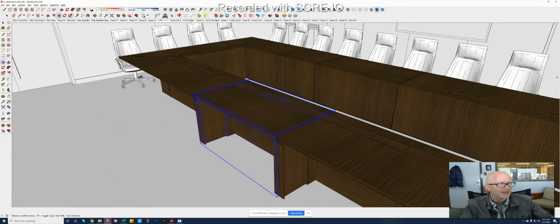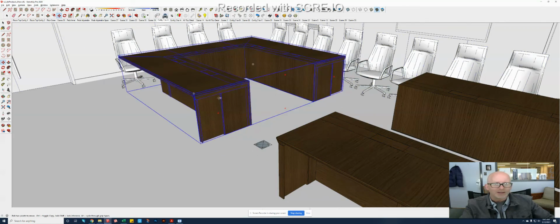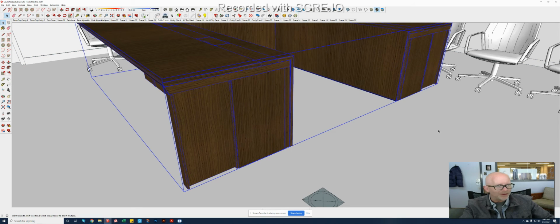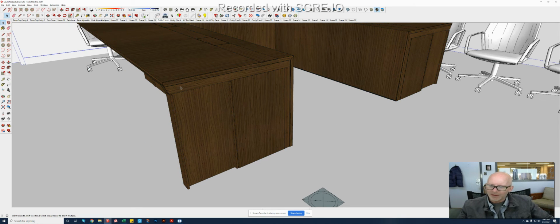When they're out of here, what we'll have on this section, at the very top here and down, is a removable piece of solid wood. It'll end up being about an 1/8 inch thick, and it'll have VHB magnetic tape on the back side of it. VHB is a very strong bond adhesive that will be on the back side of that solid wood.